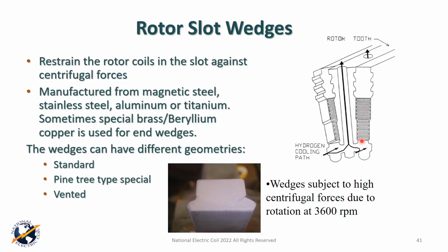It only looks at turn insulation, not ground insulation or anything else, but it's extremely accurate, and it's a reasonably priced monitoring system. We do it as a regular course as part of the running electrical tests of the high-speed balance operation to make sure that there aren't shorted turns, and if there are, what they are and where they are. And the great thing about that test is that it tells you, in general, where it's at in the coil and which pole it's on. It's really a great test.